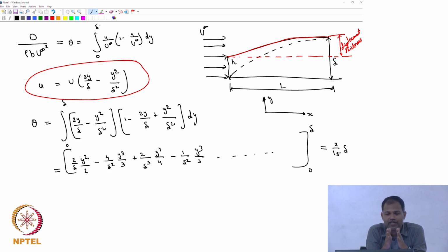So typically, whenever you have flow in very thin sections, an approximation of a parabolic profile often gives you good results. So that's the only reason. We could have done the same calculation assuming linear, and you would have gotten a good estimate. Parabolic is slightly better because the actual profile is very close to a parabolic profile.